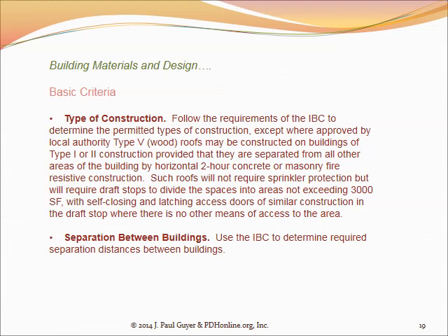Also, a point to keep in mind is separation between buildings. This is an important consideration in fire protection engineering, and it is mandated for different kinds of buildings in different kinds of situations. The point being that if a fire breaks out in one building, you don't want that fire to jump over to another building and set it on fire.